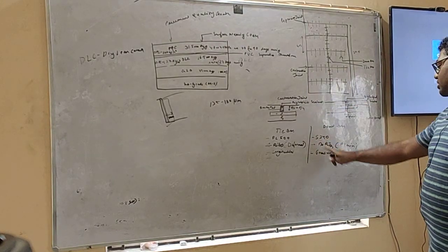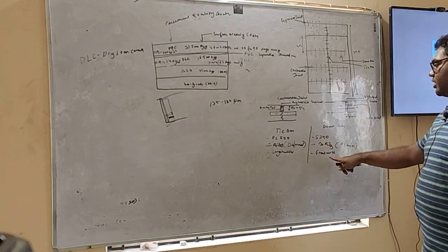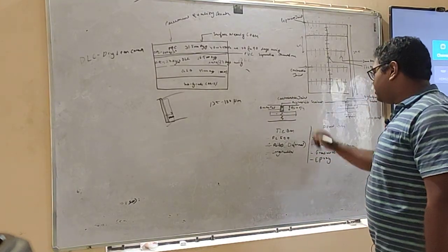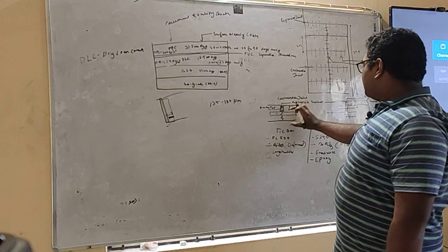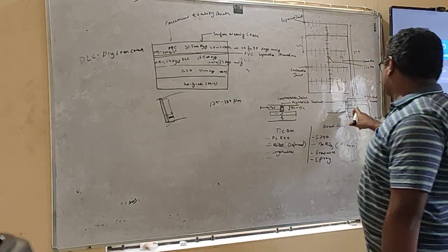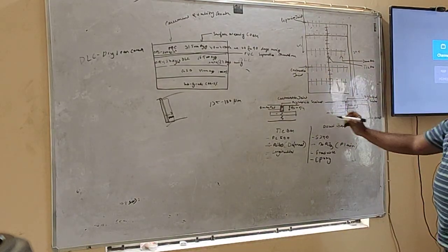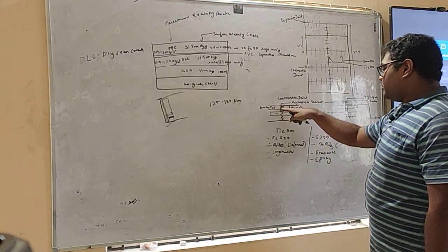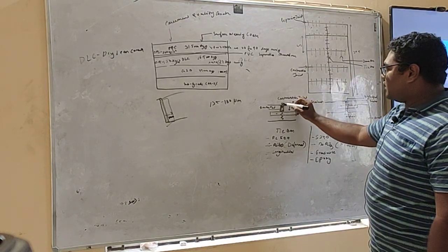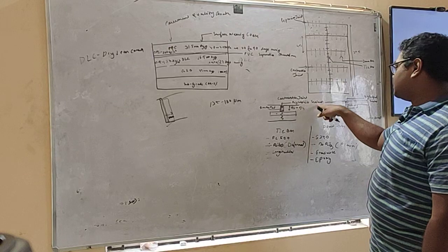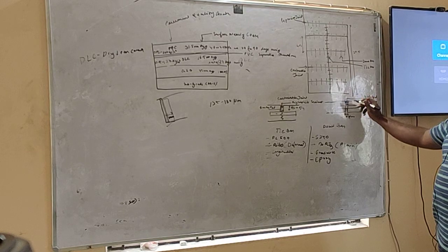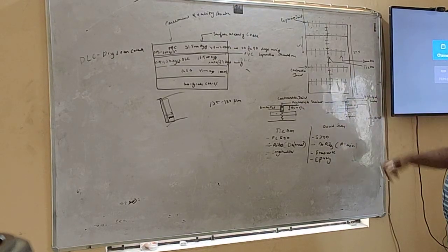It should be of S240 strength, and it should be plain, and it should be in transverse direction, and it should have an epoxy coating which makes it look green. These are basically used to prevent expansion and contraction. Here it is expansion joint and here it is contraction joint. You can see both use dowel bars, and in a contraction joint we have to give a backer rod, which is basically a plastic material, and above that we have to give a polysulfide sealant to seal it. And in expansion joint we need to give a filler board and exactly the same polysulfide sealant.